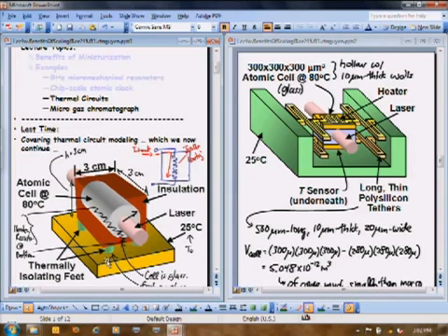Okay, so the first question that comes up, well, why is it in MEMS we can do that, whereas in the macroscopic world we can't do that? You may think, well, in the macroscopic world we want the feet because they take up less space. But that actually isn't entirely true. If I took that thing there, and I tried to suspend that by a long cantilever beam or some beam that's sort of meandering like this, you think it's going to stay up? No. What's going to happen, it's going to do this, it's going to droop. And it's not going to be as stable.